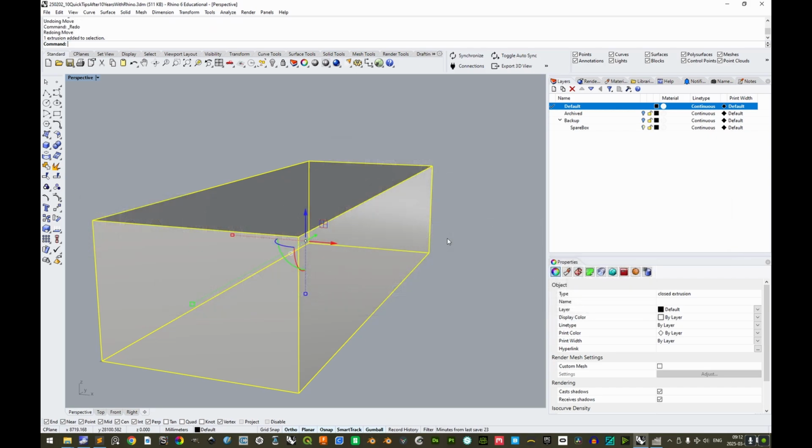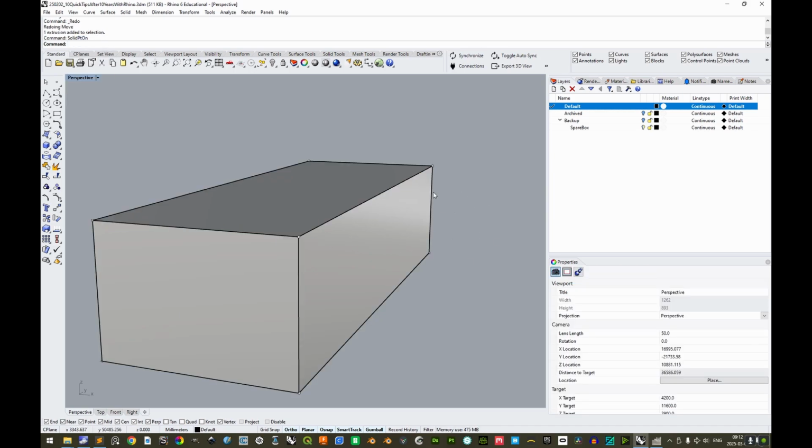You may use the Gumball tool to quickly transform objects. With Gumball active and the intention to transform these two corners, we can do it in a couple of ways. Either we do Solid Points On, and any selected object will have their surfaces' edit points available for selection. So we can select this one, and holding Alt to disable dragging and Shift to add selection, we can add this to selection as well.